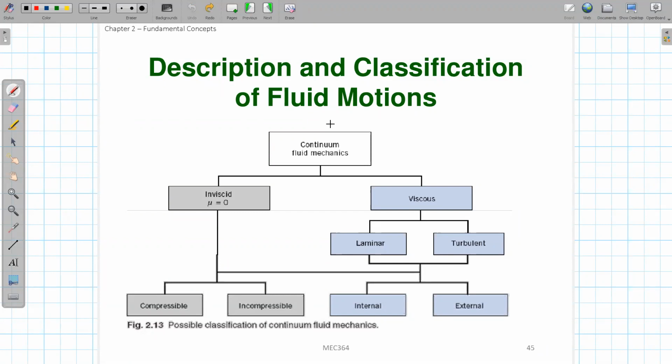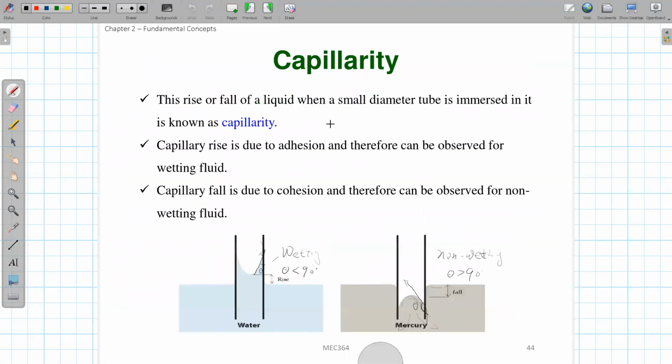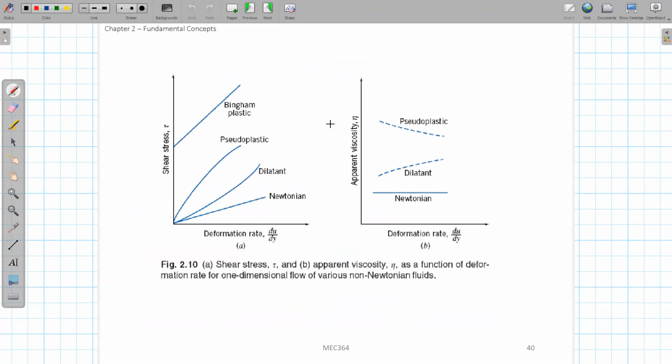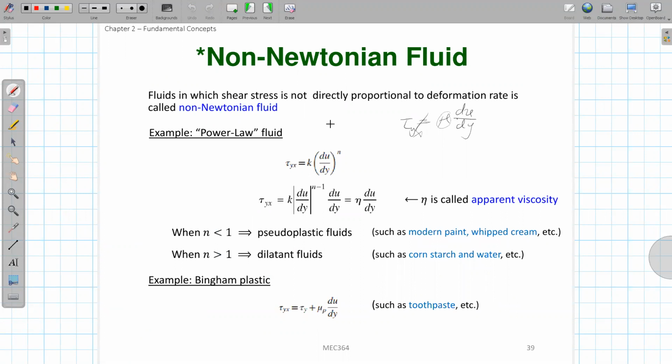Just one more thing I want to clarify. A pathline is basically a fluid particle's trajectory. A streakline is basically a line connecting all the pathlines of different particles. And the streamline is basically the curve tangent to the velocity vector. Yes, that's correct. And for steady state, they're all the same. When it's unsteady, that's when you're able to see differentiation between them all. Yes. All right, great.